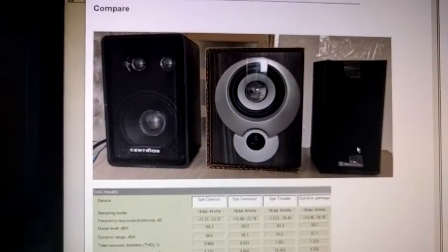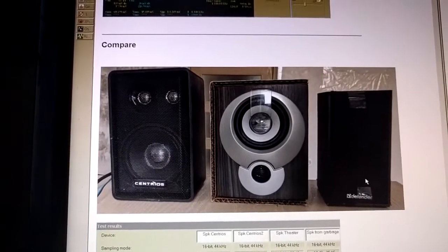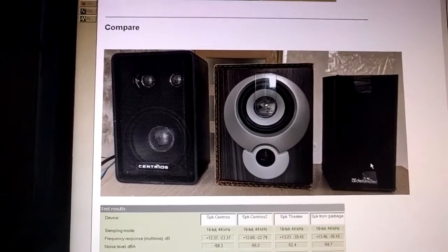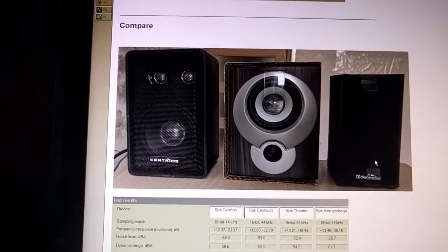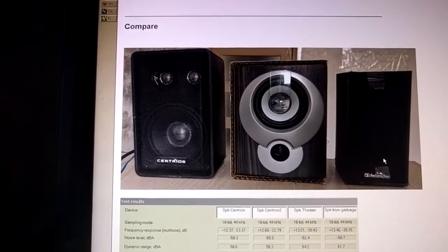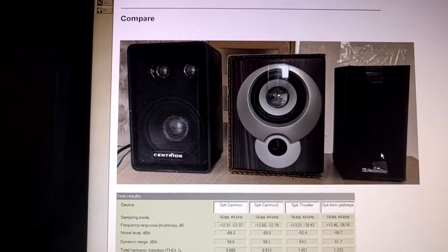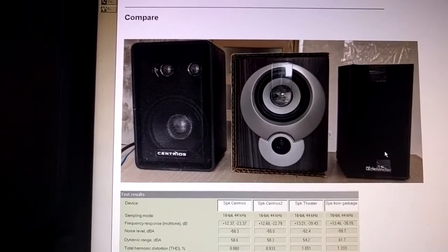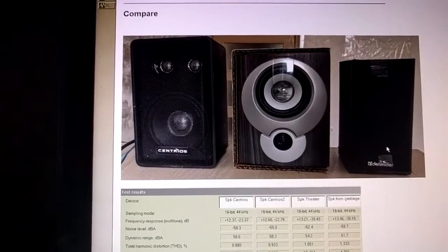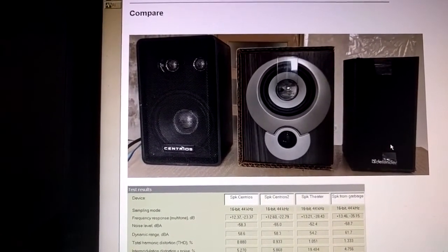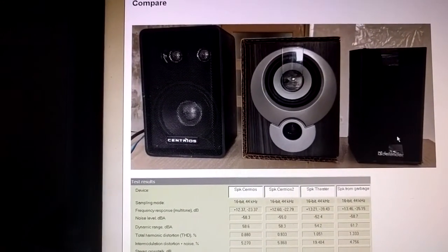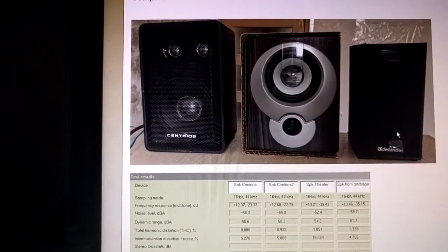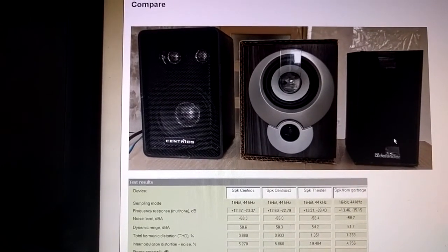And at this moment, I think I should stop this project because I'm limited by the hardware. To run the tests on those devices, you have to have a very linear microphone, and I'm not sure you can get one because it's kind of a chicken and egg problem. To test a microphone you need speakers, and to test speakers you need a microphone. So I don't see a way to solve this problem. And secondly, there is no need to do it, because even at the distortion level of 0.2% total harmonic distortion, it's more than good enough, so you don't need anything else.